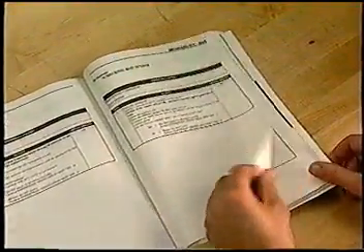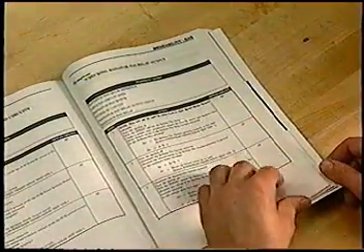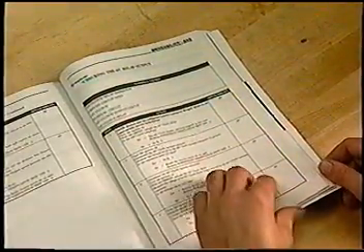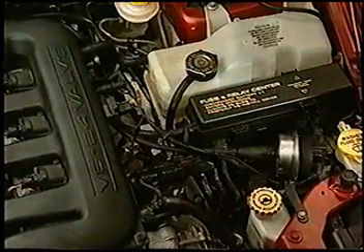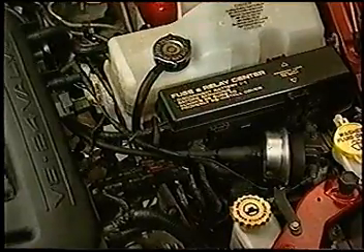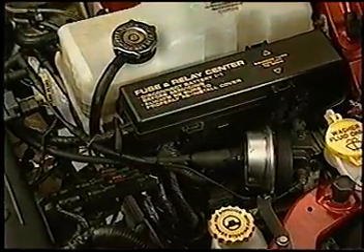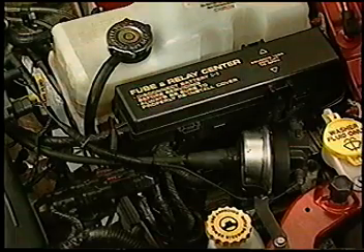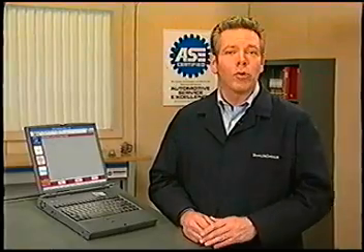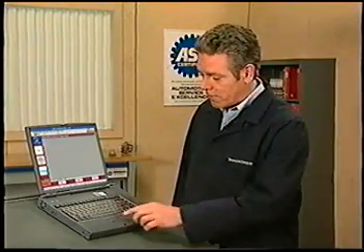If the engine seems to be losing power, you may want to check cylinder compression or check for a plugged catalytic converter or even a collapsed exhaust pipe. Remember that something as simple as an exhaust leak can mislead the PCM when the oxygen sensors report the additional air in the exhaust. Whatever the cause, just remember sometimes vehicle diagnosis requires an understanding of the fundamentals of engine operation. With that said, before we look at the changes that have occurred in the area of onboard diagnostics, let's take a minute to go over the reasons that it's used today.